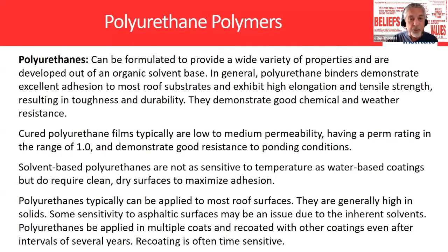You have to make 2 passes with an acrylic, because when they dry, you don't have enough mils to satisfy your warranty. Because as you know, just like with any of the products pretty much that go on our roofs, except for a couple of them, every year you lose a little bit of that surfacing on those products. They get a little bit thinner, just like TPO.